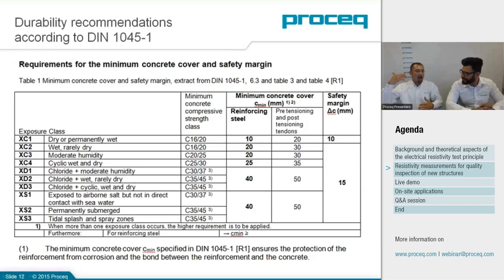And just qualitatively speaking, we have a table stating that the worse the scenario, the thicker the cover, meaning you need more protection, and the stronger the concrete. Yes, concrete strength is somehow a measure of the degree of protection, but it is not the ultimate measurement for durability. As it is today, people still pay for concrete strength. Designers put down specifications, and contractors provide and test strength.